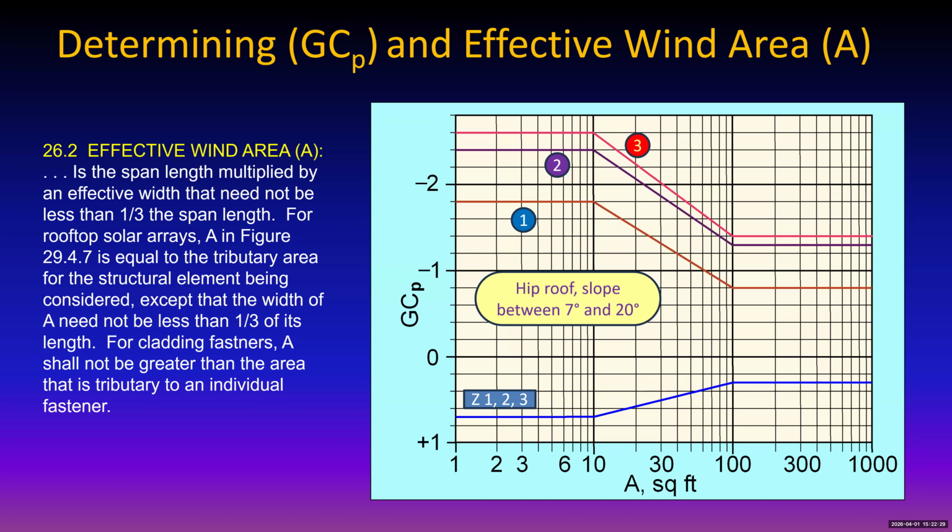You get a lower uplift rating for landscape than for portrait, and sometimes that low landscape rating is 33. So you notice zone 2 and zone 3 landscape modules with rails parallel to the long side is not okay. Again, this is a very specific thing. It's getting really picky, but it's something we see once in a while, and we would pay very careful attention to that in our designs.